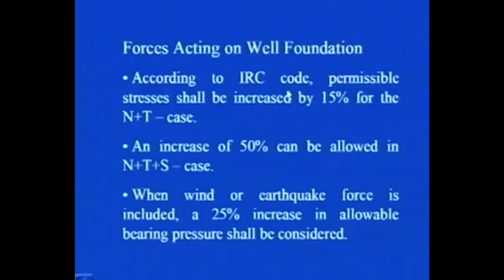So, once you decide which case you are going to take for the stability analysis of the well foundation, then correspondingly, based on these IRC recommendations, whether it is the N plus T case, the N plus T plus S case, or if you are considering wind or earthquake force, you have to increase the allowable bearing pressure or permissible stresses by the particular percentage recommended by the IRC codes.